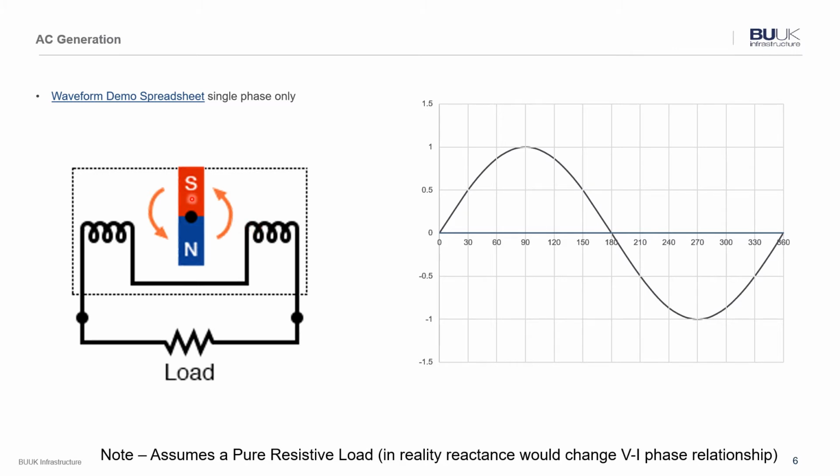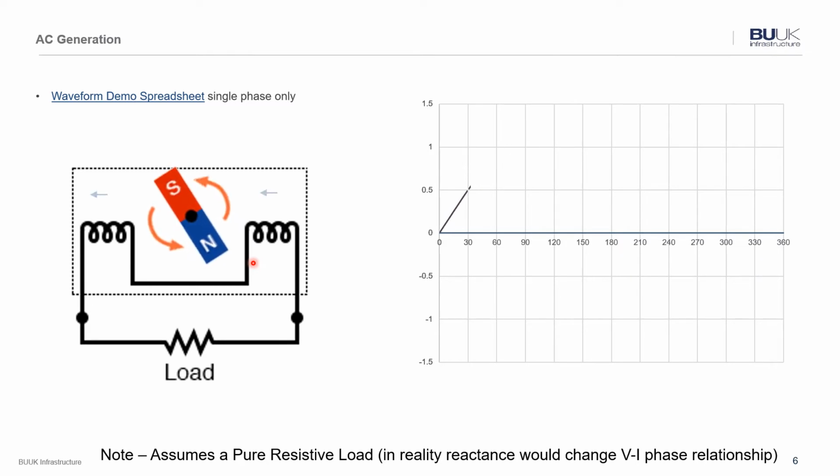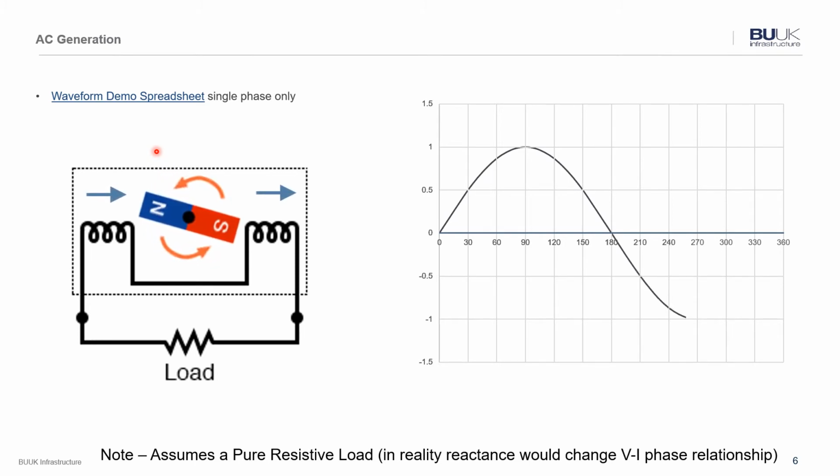If we stop the motor or the generator at any point, very quickly the induced currents will drop back down to zero. It's only as we move and rotate the magnet in the presence of the coils that we get an output. If we repeat it slowly, what you can see is as we get closer to the horizontal, we reach a peak output, and as we're moving away again at 90 degrees to the permanent magnet, the coil magnet, we end up with a zero.